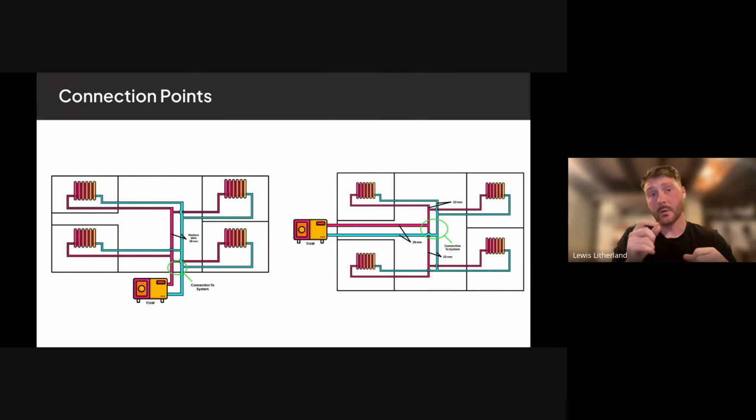If you had a heat load, as it says really small, sorry, at the bottom of the heat pump of 11 kilowatts, and you were trying to connect onto 22 millimeters pipework, you might do your calculations and work out that maybe your resistance is too high for your pump, or maybe your velocity is going to be crazy high. If that's the case and you're just connecting straight onto that pipework, again, you might say, okay, I need to repipe all that in 28 millimeters pipe. Again, disruption increases, cost increases, and time increases.